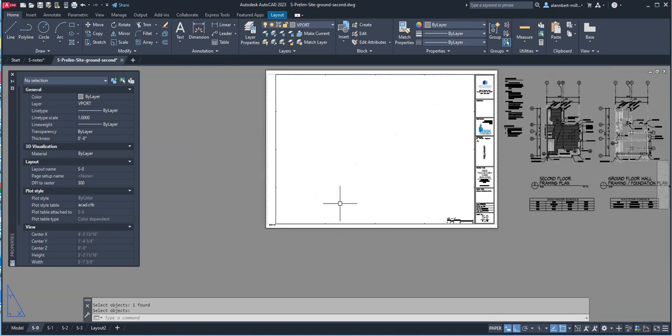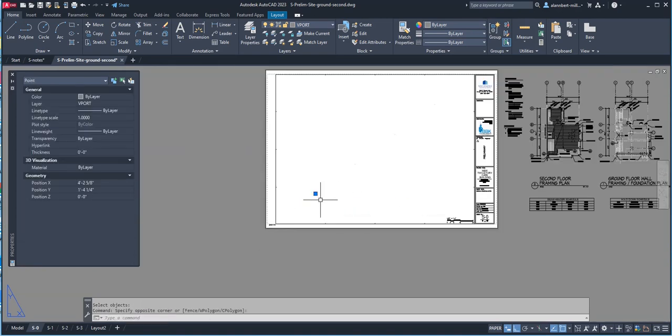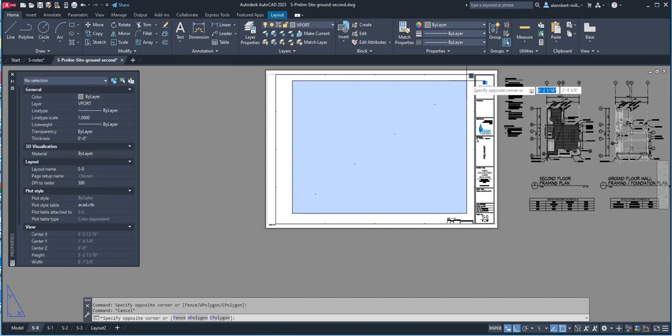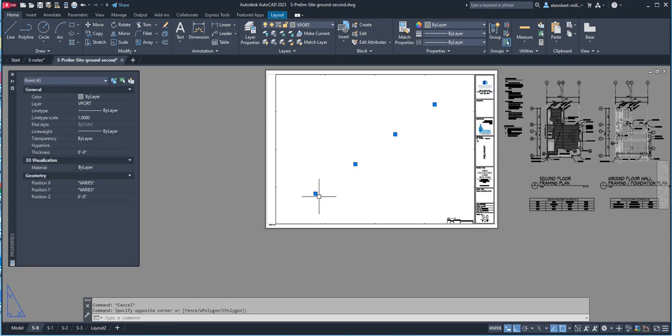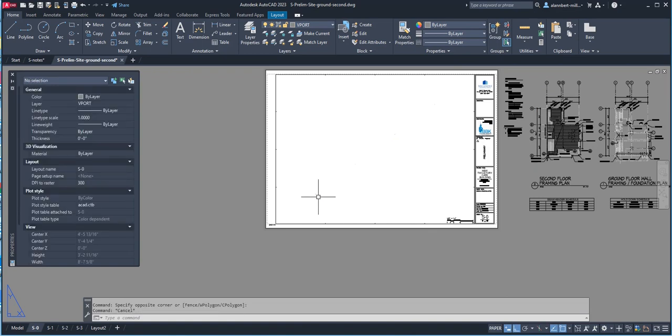If we select that, see there's a dot there, and there's another dot there. In fact, there are 4 dots here. So that's your divisions. If you do a line and then want to attach to a dot, you type in NOD, node. And so we're going to do a perpendicular, and then line again, and then we want to go node.